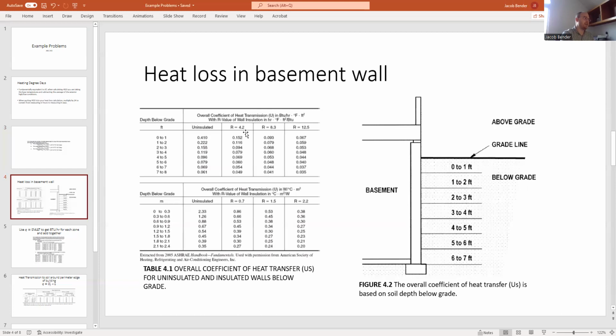The number that's in those columns is going to be the U that you're putting in your UA delta T equation. You'll notice that the amount decreases the further down you go. So in this profile view, you're going to have the most impact in the top feet below grade, and less coming out at your further below grade levels.